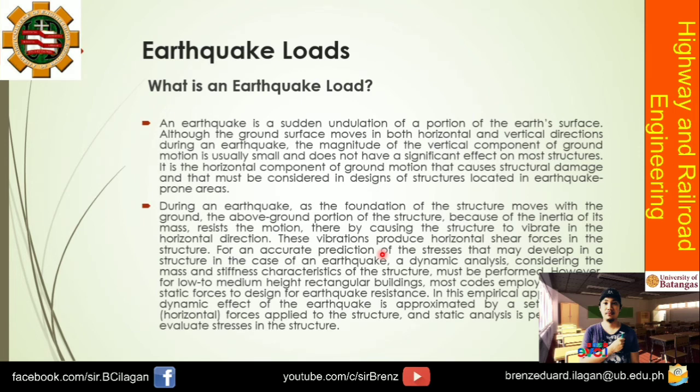So during an earthquake, as the foundation of the structure moves with the ground, the above ground portion of the structure, because of the inertia of its mass, resists the motion, thereby causing the structure to vibrate in the horizontal direction. So mag-aaroon ka nga ng swaying. So this vibration produces horizontal shear forces in the structure.